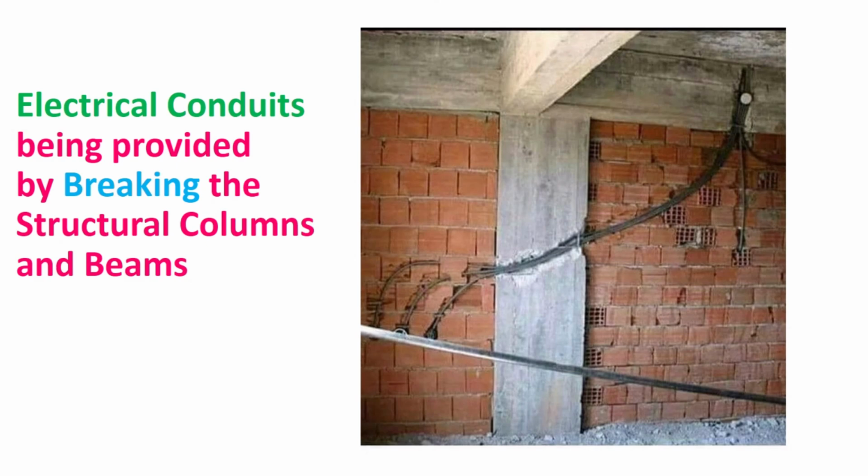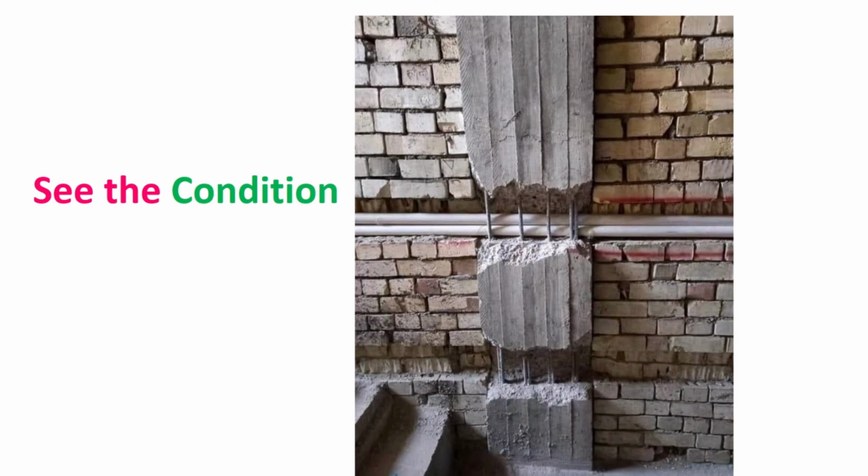Suppose you have 2 meter depth of foundation, but you have a soft strata or a layer which is having soft soil which may be at 4 meters down. So how the load dispersion will go, for how much load, that calculation he will be doing for the settlement of that particular soft strata. He is trying to tell you how it will be there for that case.